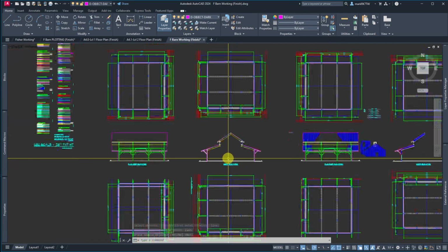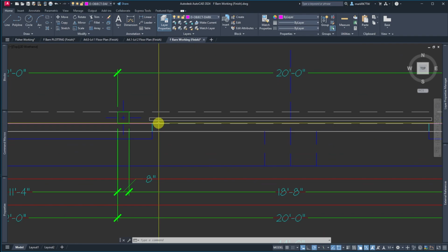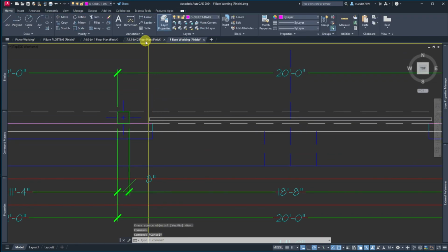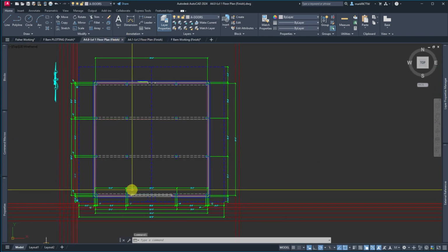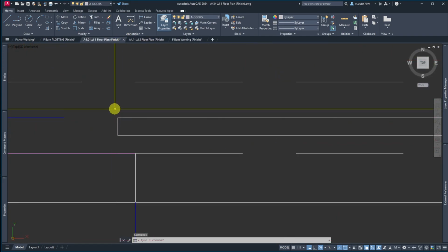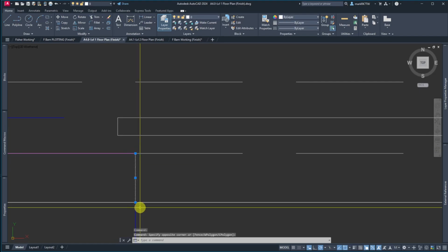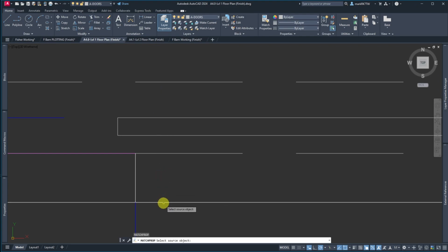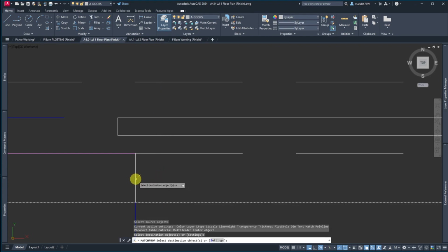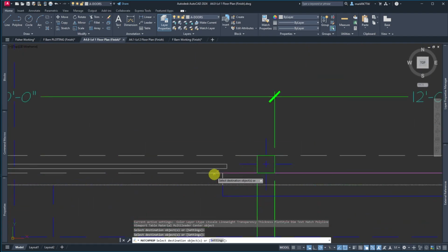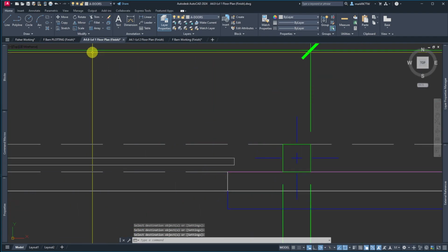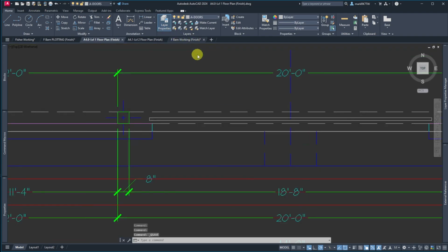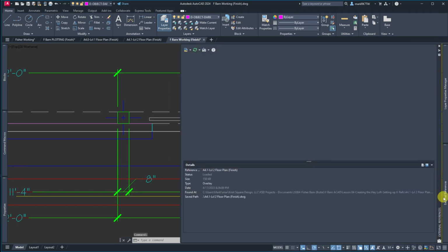And then we have, this is the south elevation. So this elevation is the door. So look at that blue. That's telling me that right on that first floor, that's still on the 0 layer. Yep. So take that one and take it to there, and then the other side of the door. Say save. When we go back to our working file, then we should have an update.